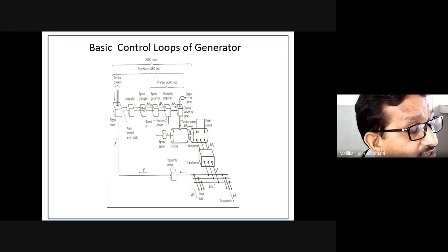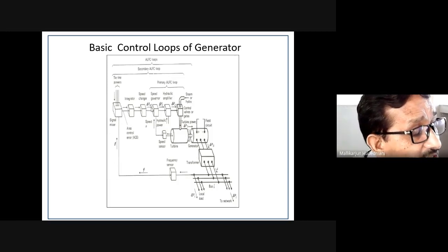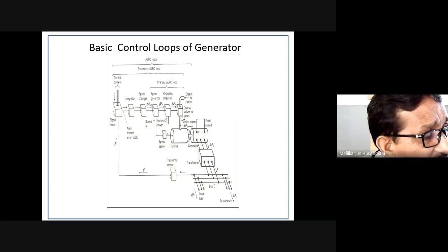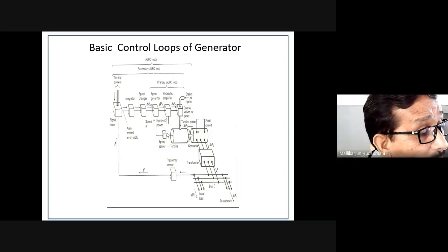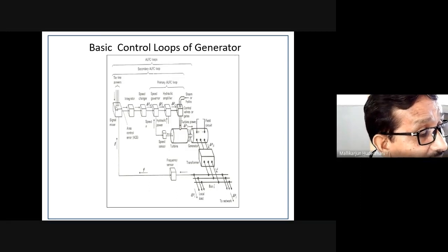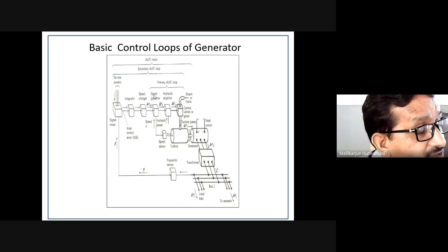This speed changer is nothing but the set point. Suppose it was set in terms of delta P ref. If there is a diminish of megawatts even after the set point is increased, it is not able to cope up, and the set point has reached maximum. Then this set point needs to be revised. Revision of the governor set point is done by the signal mixer, PI controller and speed changer action. This part supervises the need to change the set point of the speed governor.